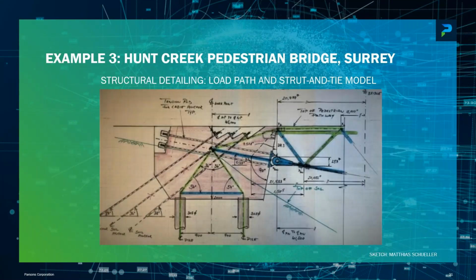And the key design item that you need to address in the conceptual design phase is this abutment, because this abutment is everything. Everything comes together here. And when you look carefully, you see strut and tie models, and you see how these separate members are actually anchored. So you have a kind of a table. I call it sometimes a pier table, but in this case, you would call it an abutment table. And there are 4 piles, so 2 in each row. You see only 2, but there are 2 basically behind the first ones. And these 4 build this table.